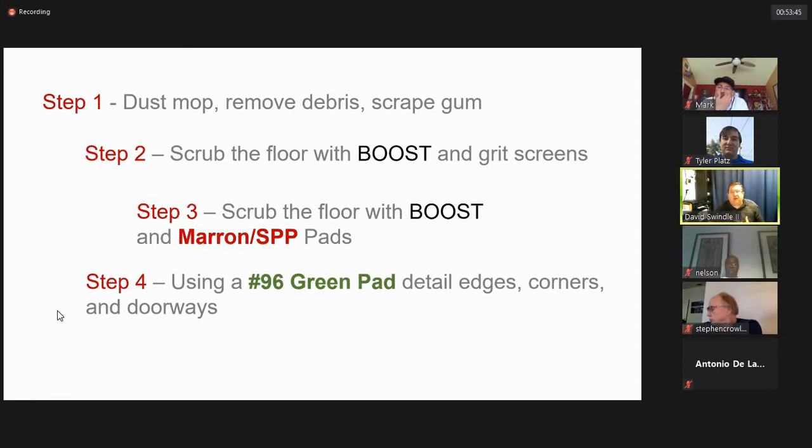Unfortunately, acrylic coatings require strippers to be used with them, and that's why we don't typically use them on gym floors. The other problem is that acrylic coatings, while very flexible, don't last as long. They wear out very quickly. So we use urethane coatings, water-based urethanes, on wood floors. They're much harder, much more durable, but they also don't stick well to each other after they've cured out.